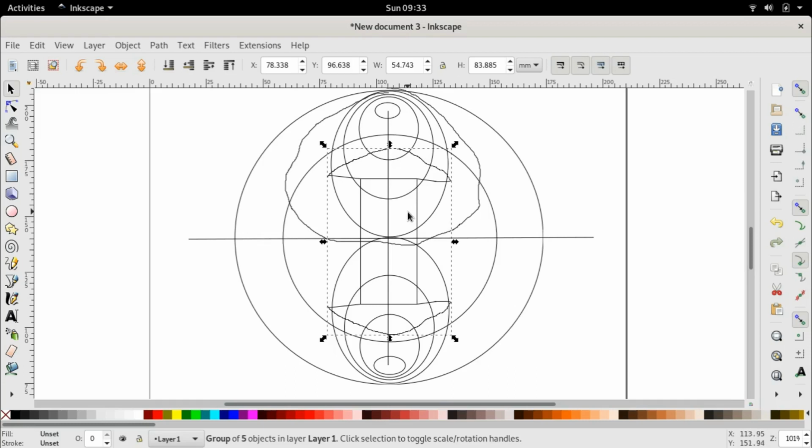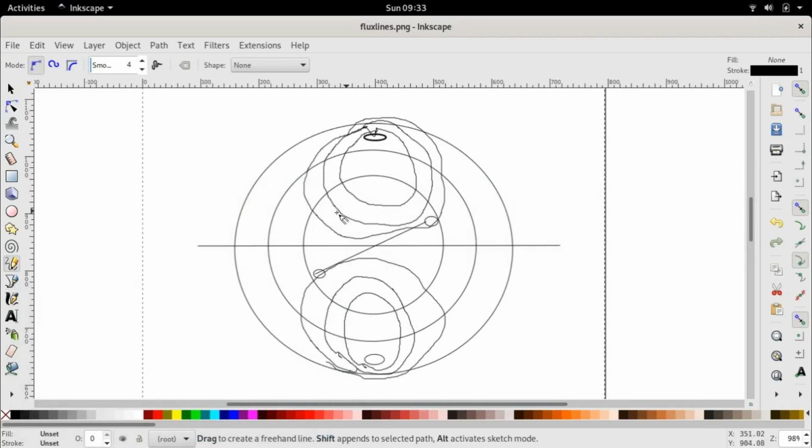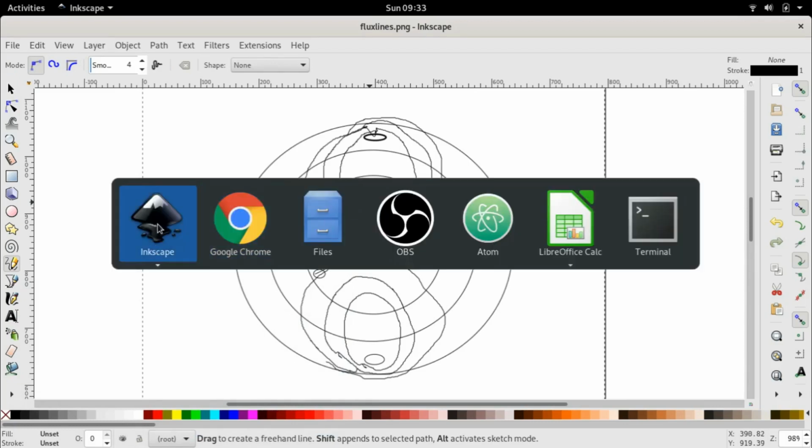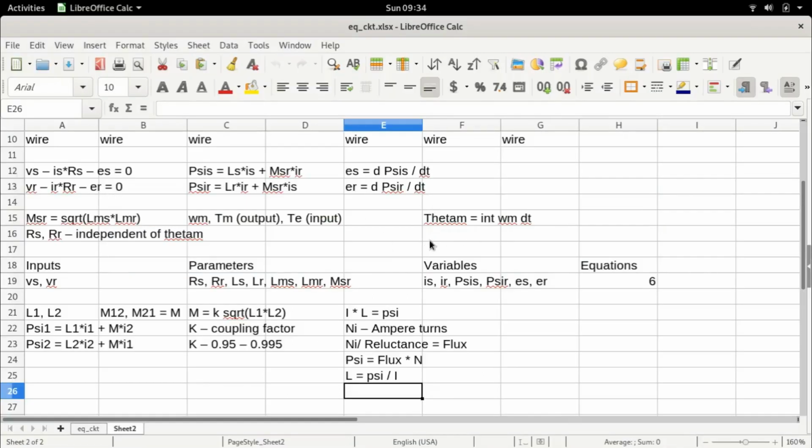In the case of a cylindrical rotor, we saw that there is no impact at all. Wherever the rotor goes, the reluctance of the flux path remains the same. However, in the case of a salient pole induction rotor, it is quite obvious that there is a difference in the reluctance of the flux path, and therefore, quite obviously, the inductance will change. Now, I will not simulate a salient pole rotor anytime soon, because it's a fairly complicated case. But this is just a glimpse into how we go back to asking this fundamental question as to how these parameters are impacted by the rotor angle.